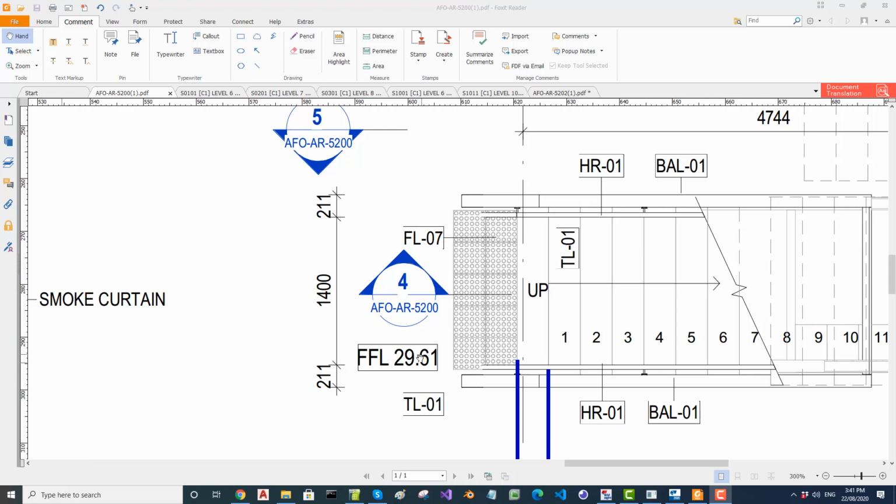So if you look at the stair width, 1400 between handrails. The handrail is normally, for this type of handrail, you got to check the drawing. I'm not going to check it now, you check it, is about 38 millimeters, and then you require a minimum clearance of 50 millimeters. A little bit more doesn't matter, but minimum required is 50, that you have to maintain. So if it's a 38, you still need another 50. If you use a bigger diameter, still you need the 50 mm clearance from this wall.